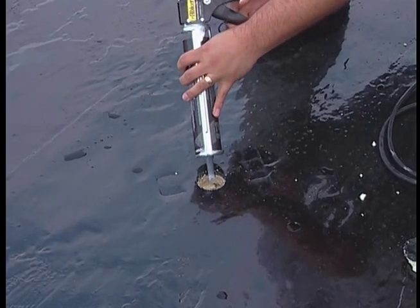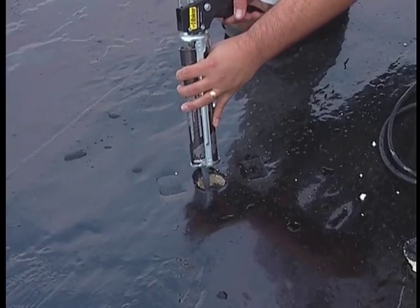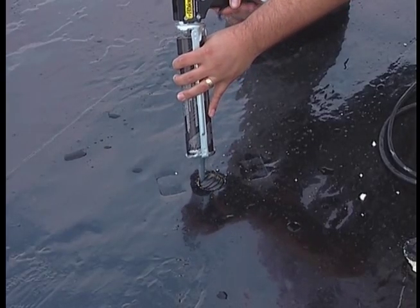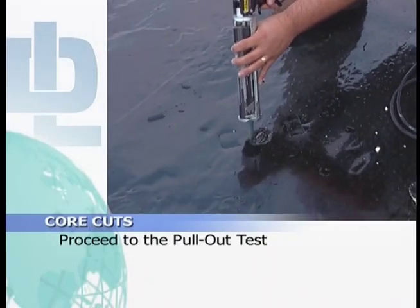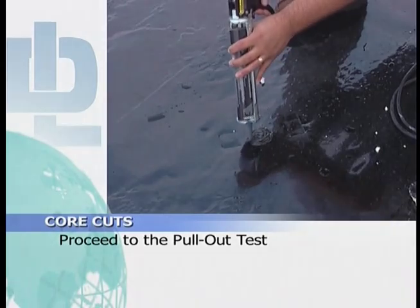After the core cut process is complete and you have recorded all the needed information, make sure that you correctly repair all cuts to ensure that the existing roof is watertight. When you're done, you can proceed to the pull-out test to decide the types and number of fasteners for the job.